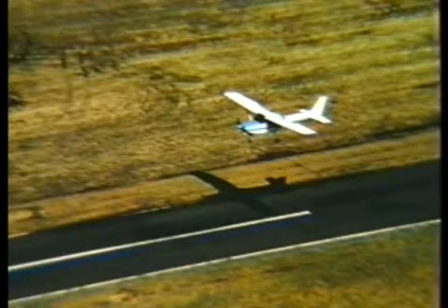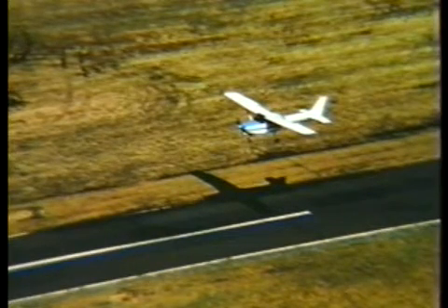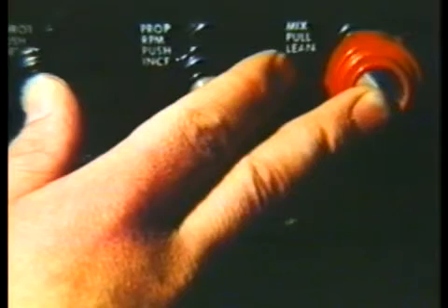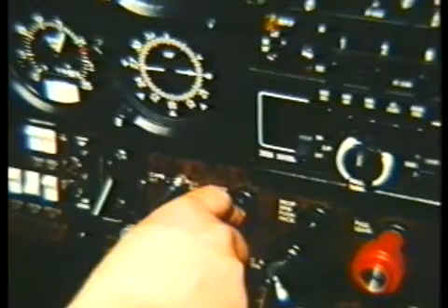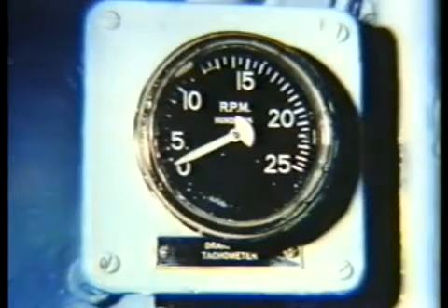Now, when you actually take it around, first and foremost, fly the airplane. Forget the tower, forget the unicom, forget the passengers. Sure, they've had a lot of coffee and need to get on the ground. They always do, but just fly the airplane. Make sure that you've applied full takeoff power and that it stays there. Engine vibration can cause those power controls to inch backwards, or a defective gauge or sensor can make you believe you've got full power when you don't.